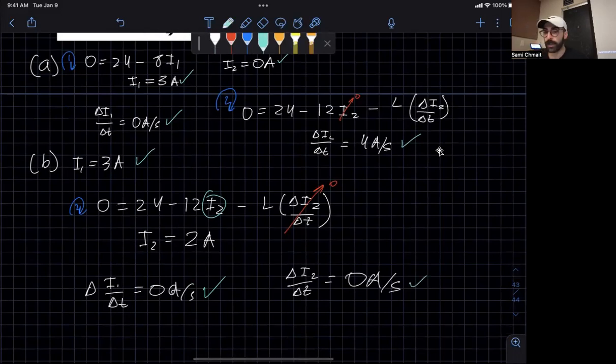So this question is very important, the important parts, like I said over and over again. And you can see how the same concept was hit over and over again. The thing to take away is, inductors act like an open switch immediately following closure. The switch is closed at time 0. So yeah, an inductor acts like an open switch immediately after closure. There's going to be no current over there. And then at steady state, it behaves like a wire. So therefore, you can calculate I2 through the way we discussed, and the change in I2 over time will be equal to 0. Okay, let me see if there's any questions on this.